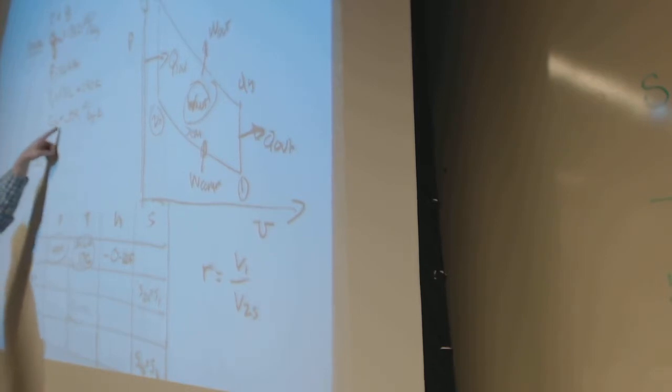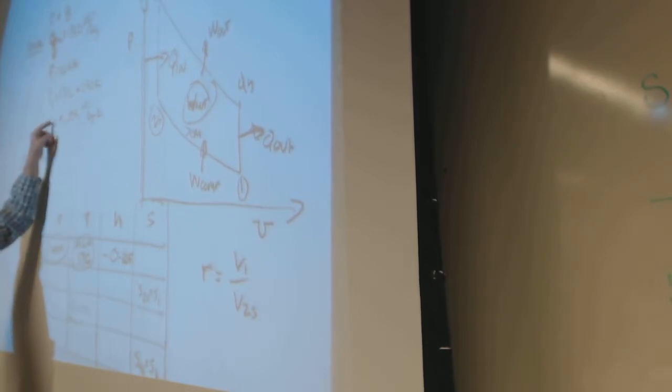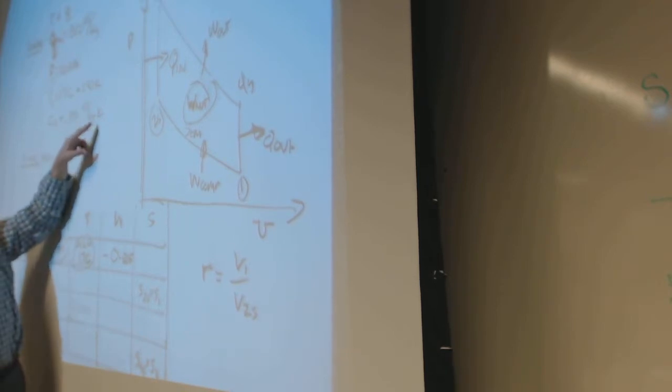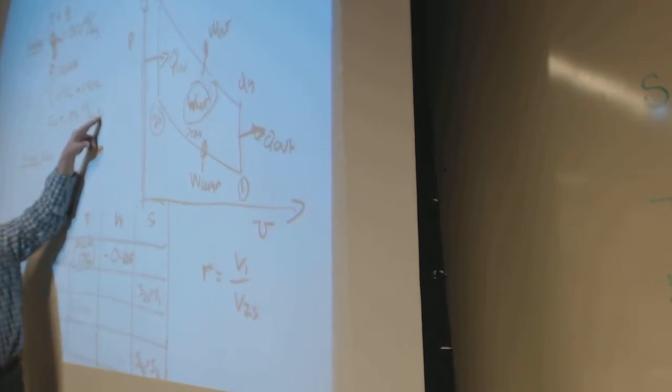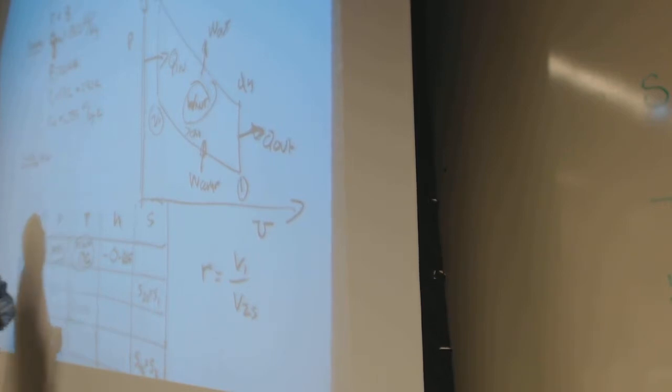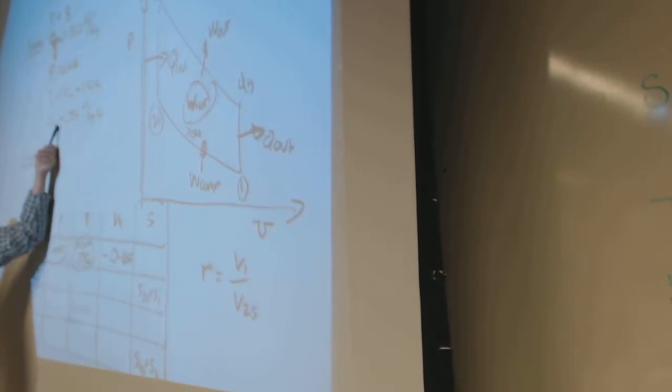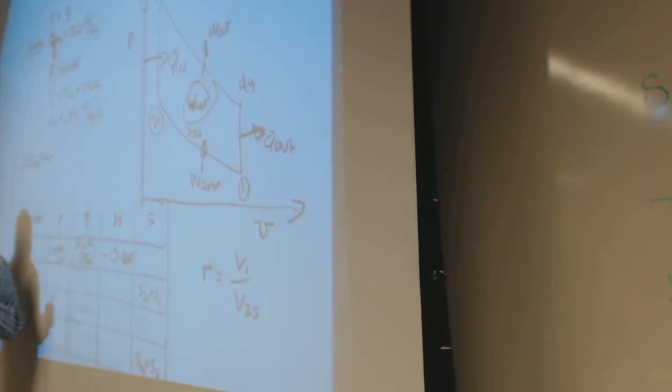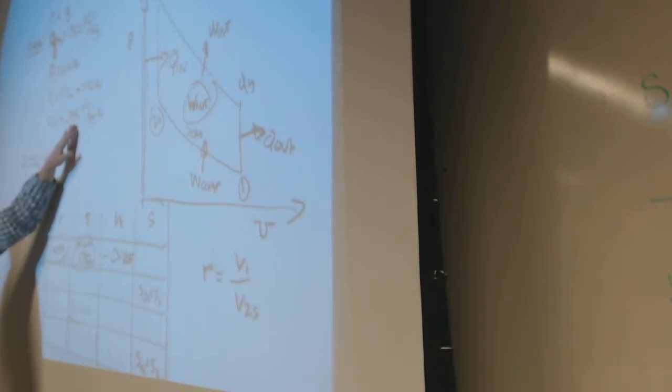And for a constant volume process, how much heat it takes to raise a kilogram some number of degrees is 0.855. We're treating this as a constant. Is it really a constant? No, it varies a little bit, but if you're close enough in temperature range, then you can get an average value or treat it as a constant.